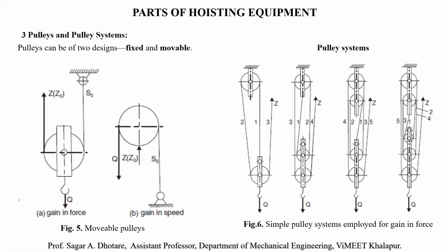In a simple pulley system, the simple pulley is mounted on one shaft. The shortcoming of directly suspending a load from the rope end, or of employing a simple pulley for gain in force during hoisting of the load, is that different parts of the rope are in one plane, and this may allow the load to swing freely at right angles to the plane of the rope.